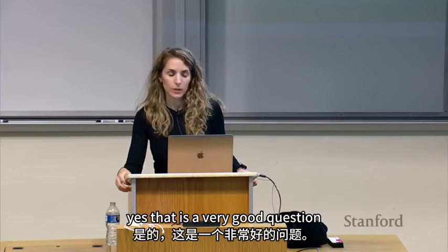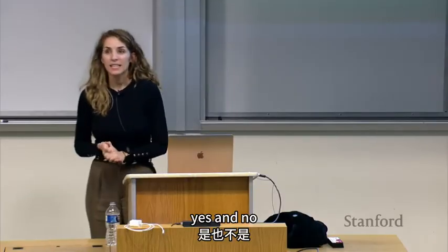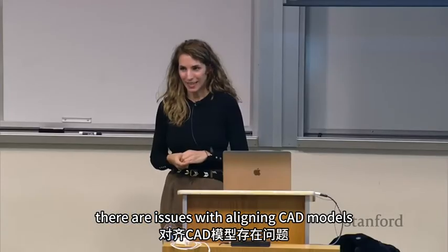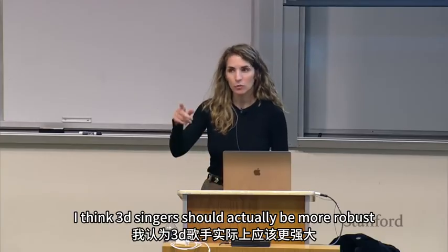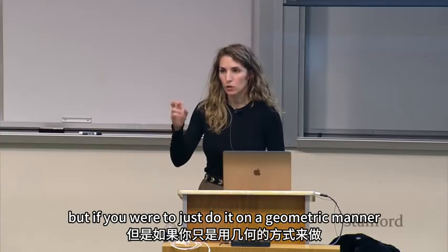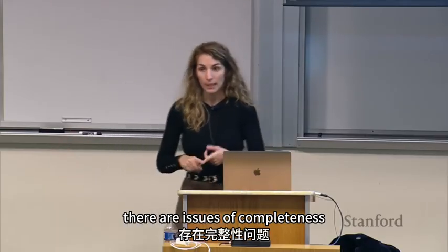Yes, that is a very good question. There is a reason why I didn't touch upon that. We're actually working on it these days. Yes and no, and I will tell you why. There are issues with aligning CAD models or building information models with existing point clouds. I think 3D scene graphs would actually be more robust for performing the alignment, but if you were to do it in a geometric manner directly on point clouds, let's say you can sample points on your CAD model, there are issues of completeness.